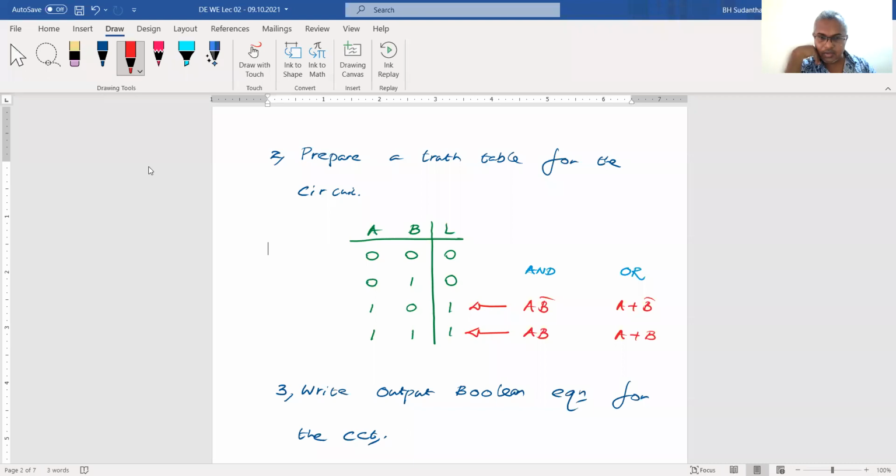What do we need here? We want to take these two. Why? At these two occasions only, we have to turn on our alarm. Okay. To do this, here we have used AND operation to take this term out. And here we have used OR operation. Which one is the correct one? Both should not be correct, but one of these should be correct. Which operation can we use to consider this? AND operation or OR operation?